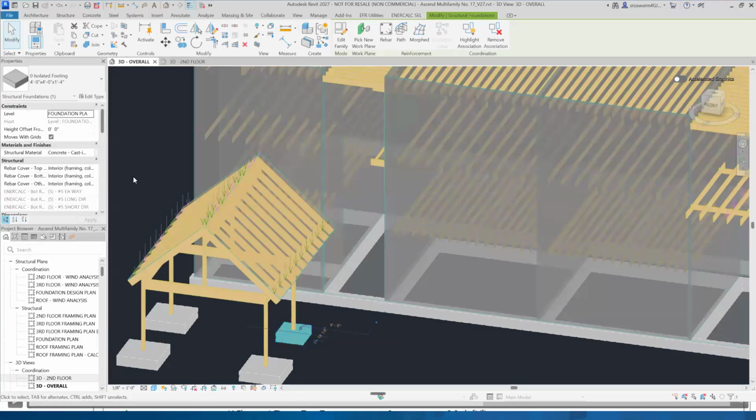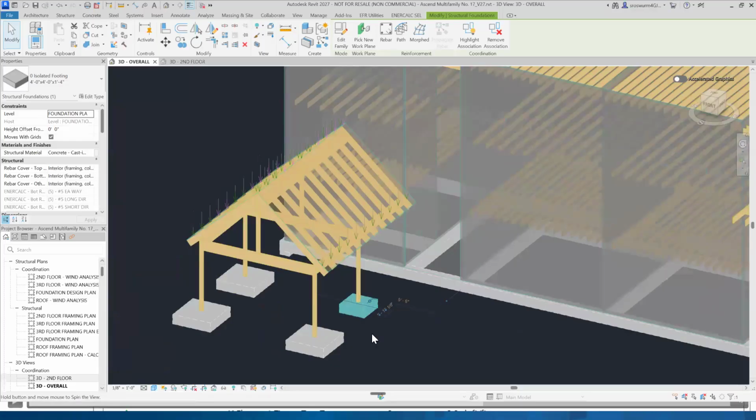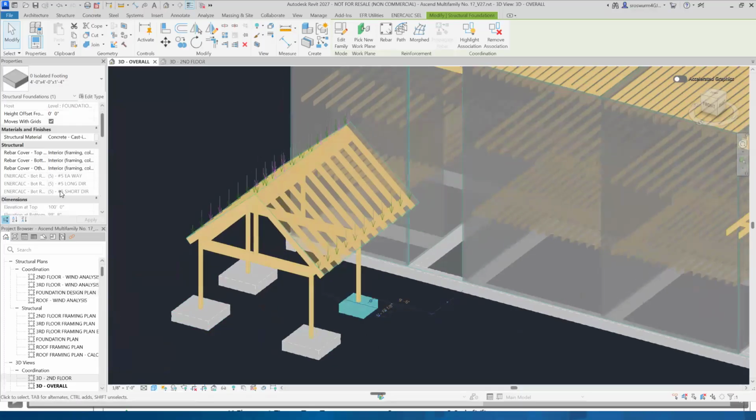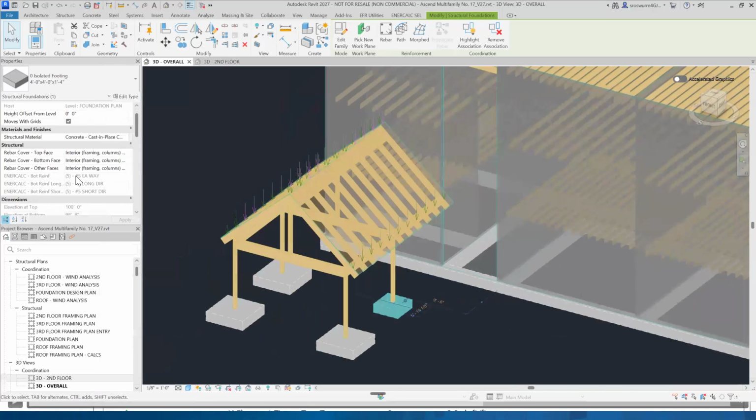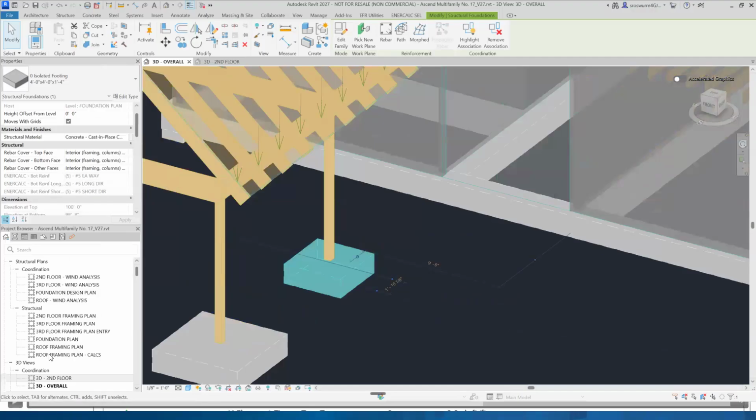If I select this footing right here, Chelsea, you can see my Revit model right now, right? Yeah, I can see your Revit model. I see those parameters over off to the side. Yes. And so if you look in the properties pane when we select this footing, you can actually see where those ENERCALC parameters have mapped back to here.